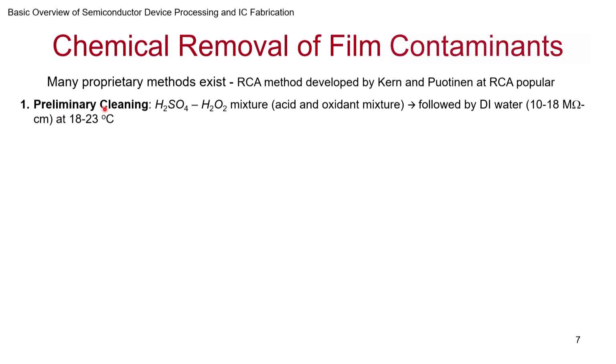So the preliminary cleaning actually uses H2SO4, H2O2, a really potent mixture. Usually it is dehydrated H2SO4 and H2O2, and you give a quick clean with that, followed by DI water. Now what is DI water? DI water is deionized water. So you get rid of all the ions that are there in the water.